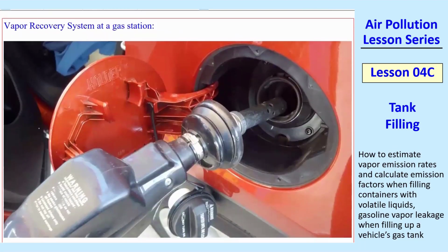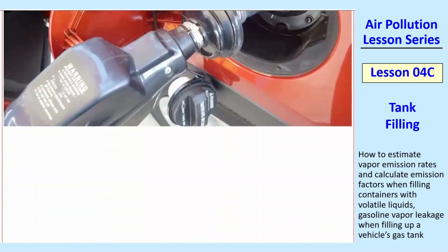Around here in State College, we don't have these kind of gas tanks. If you look at the nozzle, it's just a solid cylinder. But if you look closely at this one, I took this near Pittsburgh when I was visiting one time, and you can see that there's these holes here. So what's going on here? There's also this rubber cap that fits real snug over your opening for the gas to go in. And so here's your nozzle and the trigger and all that. And how this works is it's actually a tube within a tube. And let me draw this for you, and then I'll talk about it.